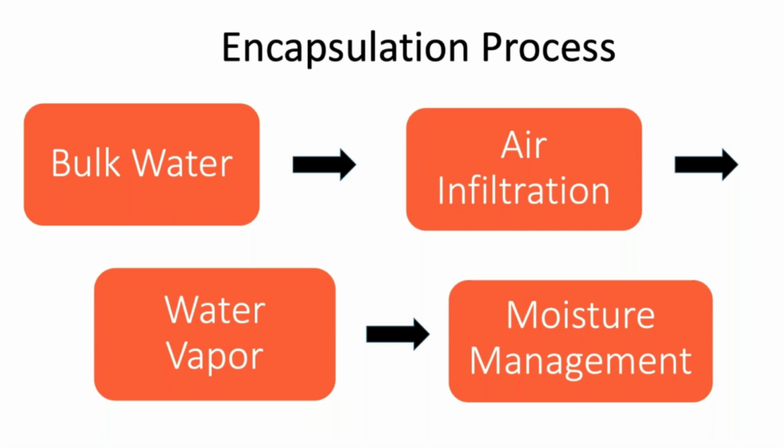You may find that it's prudent to add French drains to the bottom of these downspouts in some cases. In cases of extreme water intrusion, exterior grading may be required to divert the water away from the foundation. For today's exercise, we're going to assume these issues have been corrected or aren't an issue. In my experience, the majority of crawlspaces don't have major issues with water intrusion. With air infiltration and water vapor, these steps will mainly be addressed with our moisture management step.